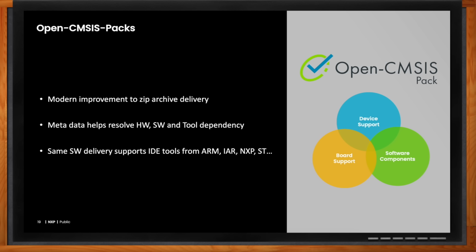So the other thing that people are wondering about is it will still leverage some of the tools. So the IDEs will support Open CMSIS packs, but also the configuration tools, the things that generate that additional code for clocks, pins, peripherals that people depend on. That is now working with Open CMSIS pack projects. We're very excited about this, and there's going to be a lot of training and new support coming out in the near term for people to explore Open CMSIS packs on their own.